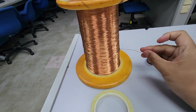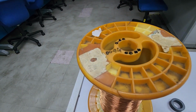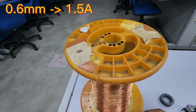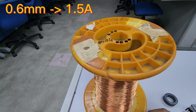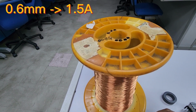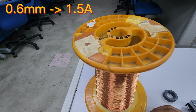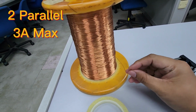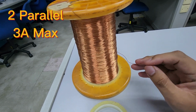This one is 0.6 mm. It can withstand around 1.8 ampere. But don't use 1.8, I suggest you just set it to 1.5. If you need to withstand 3 ampere, you have to parallel two wires together.